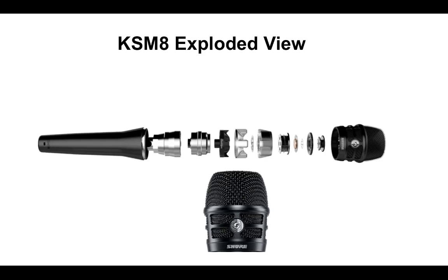So it's by far the most waterproof dynamic mic we've ever done. And that's a combination of the grill design, having that cloth in there, and because that second diaphragm seals the entire system, there's physically no entry point for water to get into the microphone. So water can't get in and fill any cavities up with anything.